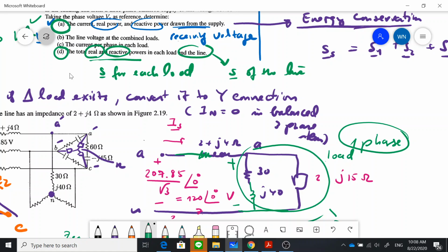You can see that you know the Is and you know the voltage at the source, right? And that creates the current flowing through the line, which is equal to, in this case, 5 amps flowing into this one. Now you can compute the voltage drop across this impedance, right? So the voltage at this point is essentially the voltage difference between the voltage at the source and the voltage drop on the line. Okay. Now you could answer the second question.